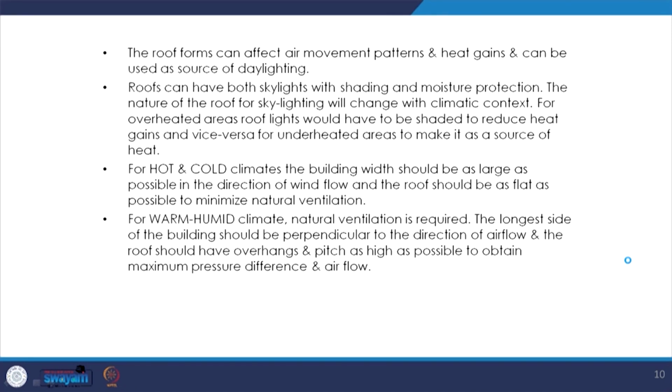Besides the air movement and solar radiation and controlling the air temperature, these elements also help in controlling the daylight. Suppose we plant deciduous trees towards south. So in summers, these deciduous trees would shade the building and control the direct radiation and also the daylighting, while in winters when they shed their leaves, they allow a lot of sunlight and daylight to penetrate inside the building. So together these elements control a lot of environmental parameters.